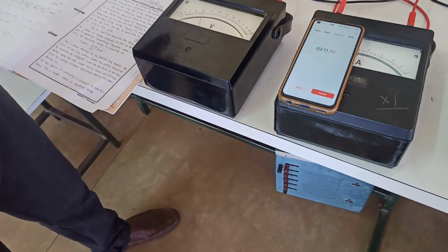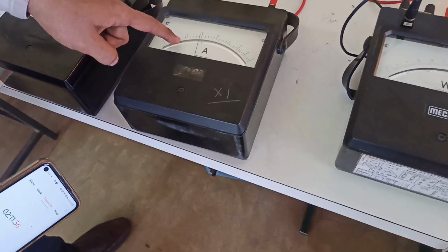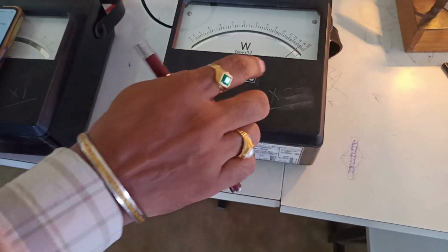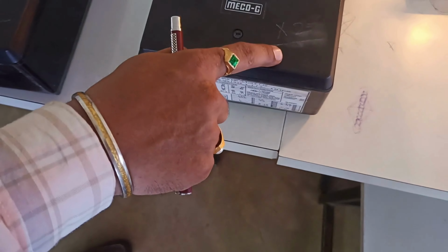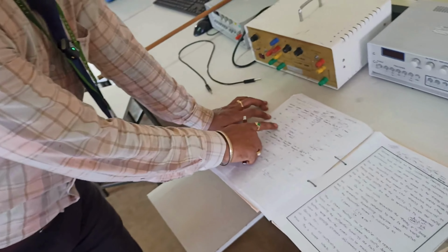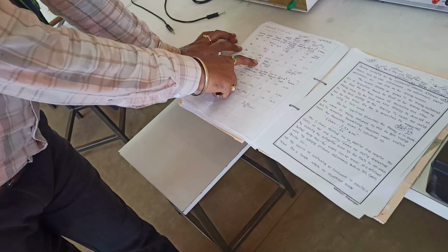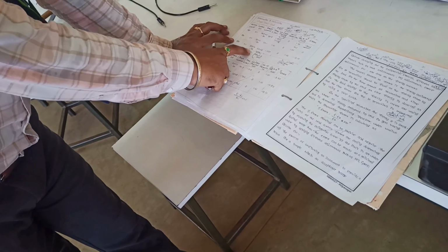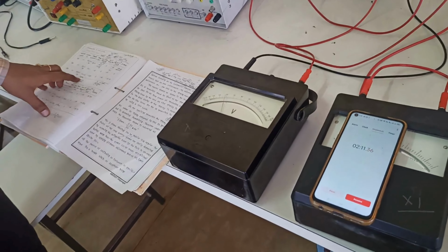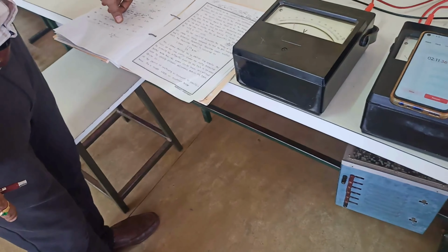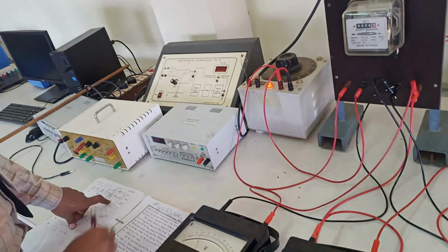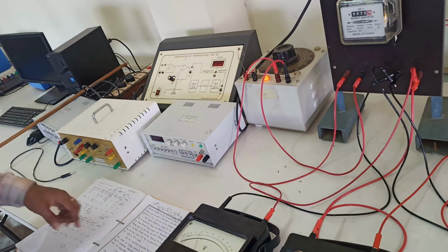At 120 volts, the current drawn by the equipment is 0.5 ampere, and you can see the wattmeter is already consuming 28 watts, so 28 watts into 2. You have to write down the readings. Voltage is 120, current is 0.5, and the power drawn by the equipment is 28 into 2, and the time. The time taken for 2 revolutions we write down, then automatically you get the watt hour calculation. And from the number of revolutions divided by 1200 you get the error.